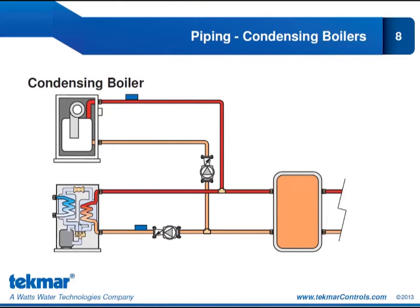It actually varies depending on what type of boiler we're using. So if we have a condensing boiler, the best way to include it into the system is on the heat pump side of the tank. The reason we do that is because condensing boilers will give us the highest efficiencies when the return water temperatures are lowest. So that's what's going to allow the condensing action to take place.